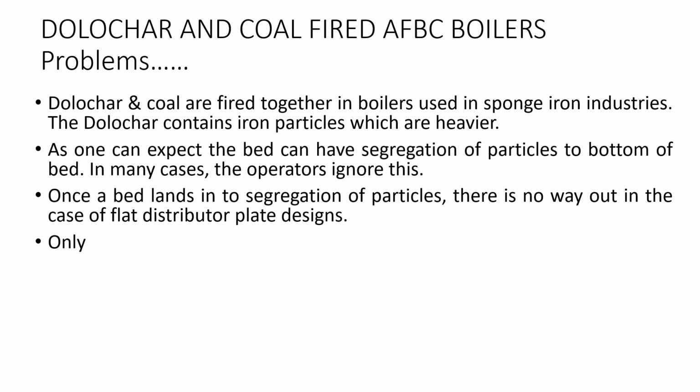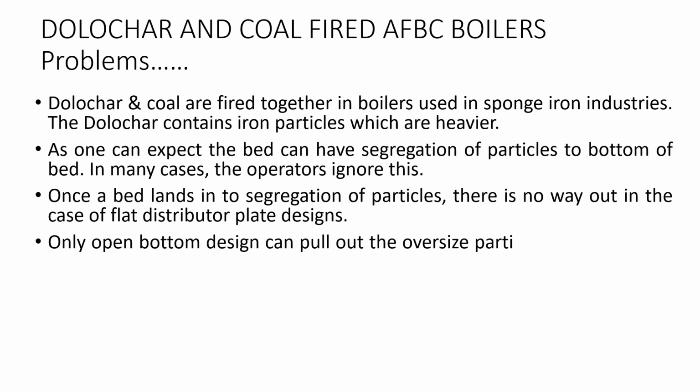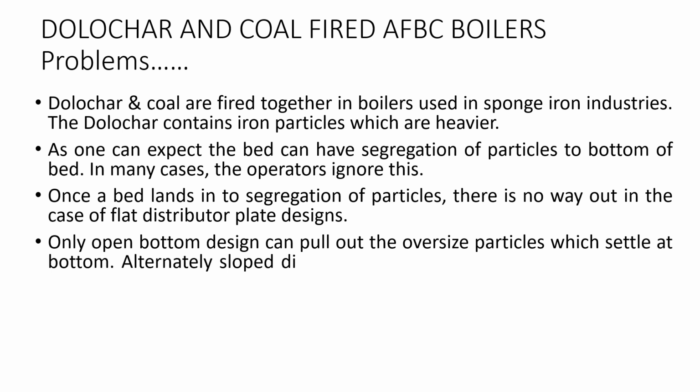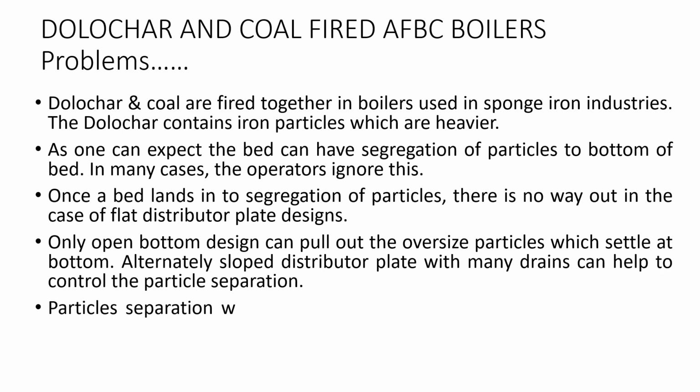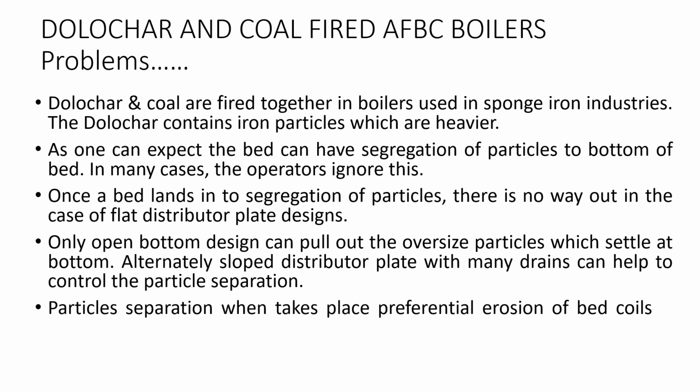In many cases, the operators ignore this. Once a bed lands into segregation of particles, there is no way out in case of a flat distributor plate design. Only open bottom designs can pull out the oversized particles which settle at the bottom. Alternately, a sloped distributor plate with many drains can help to control the particle separation. When particle separation takes place, preferential erosion of bed coils is seen.